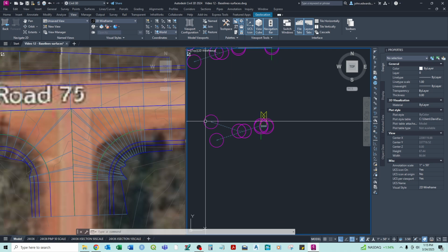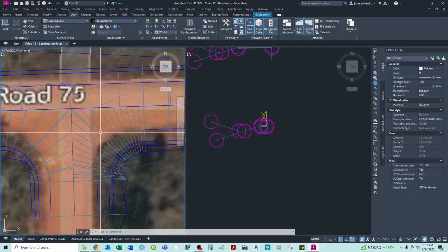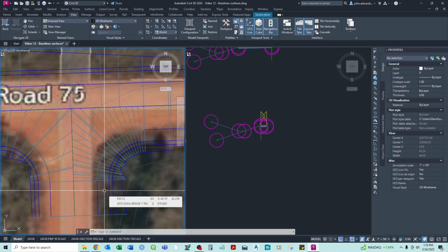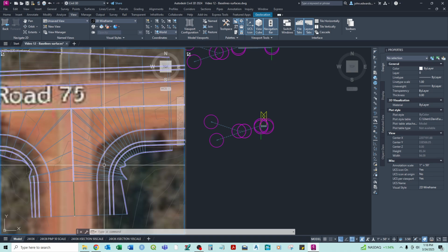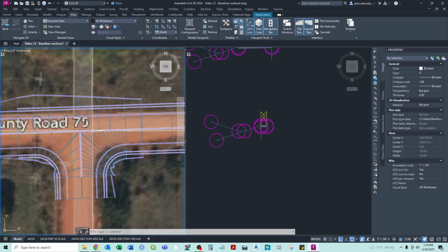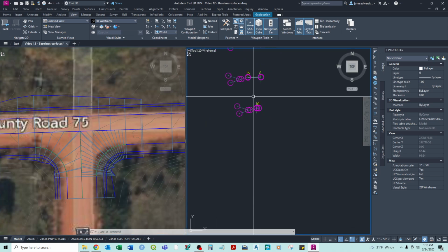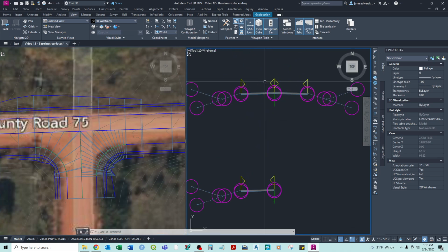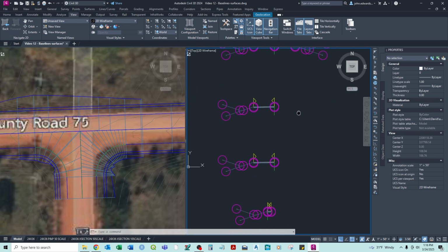And that can be the tricky part of doing this if you have non-standard geometries that you need to match up. So sometimes this may be easier to do just manually and bring these in, draw the feature lines, and just set all this up. But as far as roadway intersections, it's pretty straightforward. You have your typical section, your main assembly, and you just follow it along.